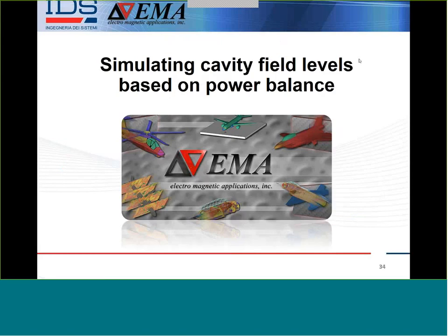Okay, so antennas, there's a lot more to that. There's a lot of training we can talk about. We'll follow up with some more webinars, or you can reach out to us if you have questions about how to pull that off. But I want to talk about another thing that is power balance method. So this is a trick to do the coupling to cavities on vehicles or devices without having to do that brute force full wave simulation with a cluster of GPUs.